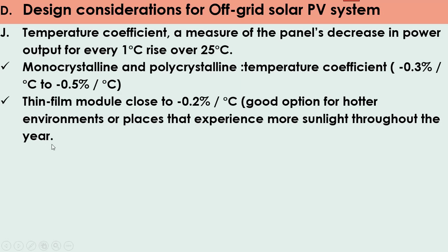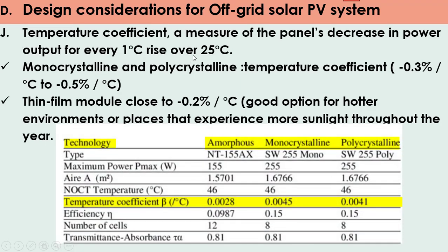The other important criteria is the temperature coefficient. The temperature coefficient represents a measure of the panel's decrease in power output for every 1 Celsius rise over 25 Celsius.